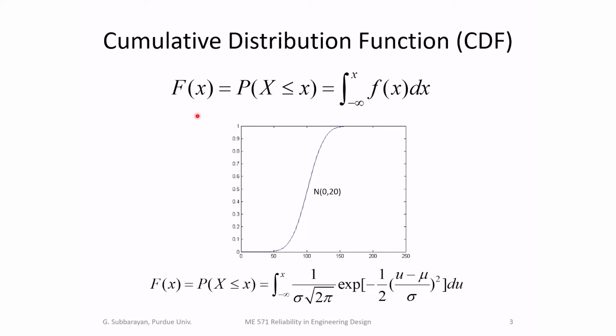So think of the cumulative distribution function always as the fraction of the total that has failed. And the CDF has the form that you see here, and it always starts with 0, because at start of the test, 0 of the population have failed. And at the end of the test, all the samples have failed. Therefore, it will always end with 1. And how it rises depends on the specific mathematical form of the PDF that we've assumed.